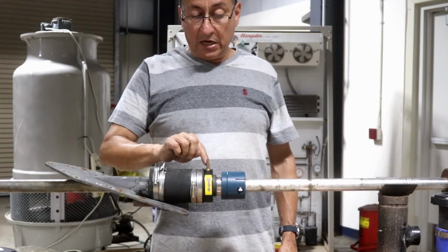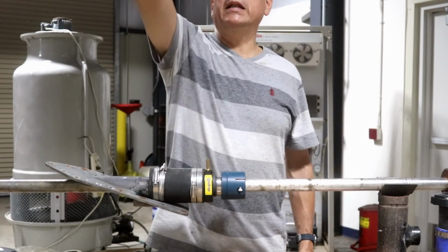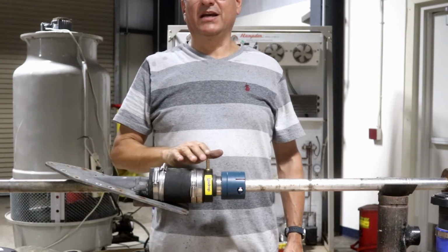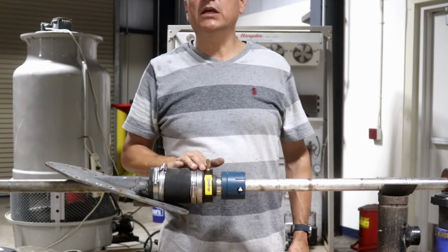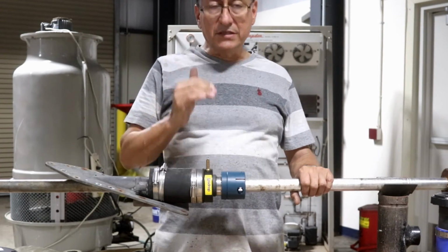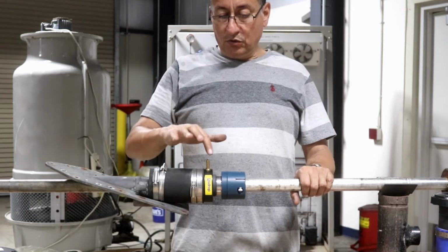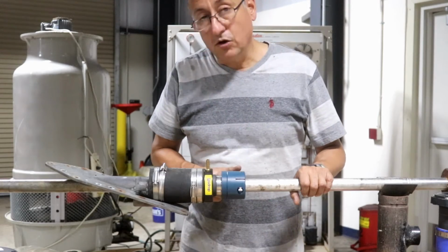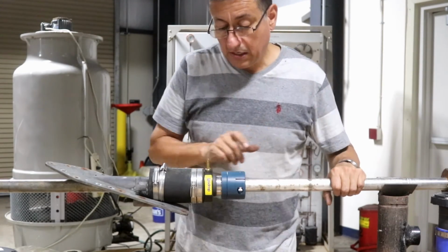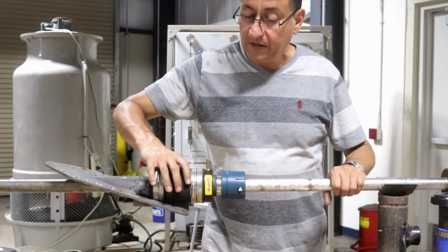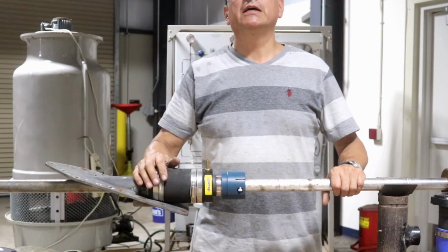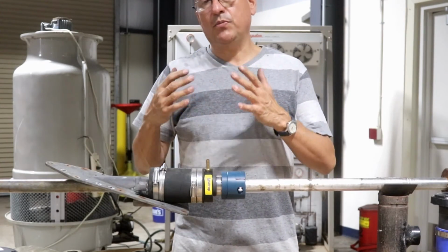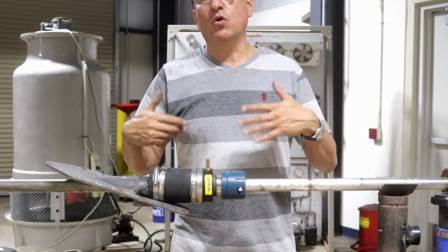Normally you need to put this clear hose with an anti-siphon over the water line in order to verify where is the level of the water line. This is a good indicator of the level of the water line inside of the engine room. Those are the fittings to verify that the water is entering. This is the stainless steel collar that is together with the shaft, and this is the graphite that is fixed with the stuffing box and the flange. This is the PTS system. This is a wonderful system that the people use every day, more and more common.